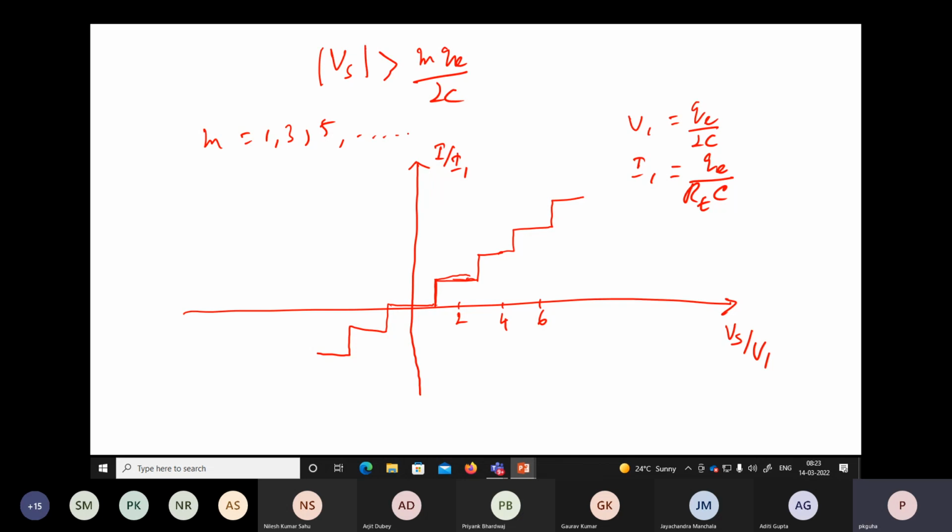So far we haven't considered any transistor. We just talked about a quantum dot and two metal contacts at the two ends, which is basically creating a capacitor structure. There is one capacitor from the quantum dot to one junction, and another capacitor from the quantum dot to another junction. So there are two capacitors, and in between, sandwiched, there is a quantum dot, and we are applying a source, that is a supply voltage, and seeing the movement of electron tunneling through these junctions to the quantum dot and from the quantum dot to another junction, so that we can get a current in the circuit, right?